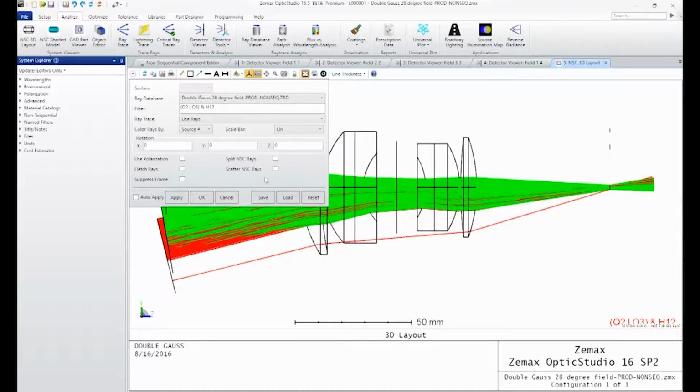just that. So rather than looking at all of the rays that meet the filter condition within this ray database file, you can actually select some number of rays. And the syntax for doing so is shown here. So it's curly brackets and then the number sign. And then you select how many rays you want to see. So in this case, I'm going to say that I want to look at the first 50 rays that meet the filter string condition from the ray database file.